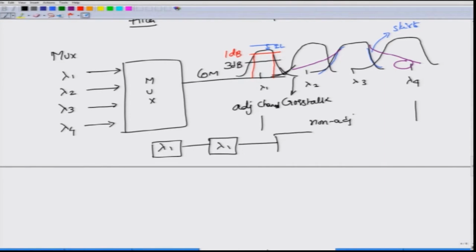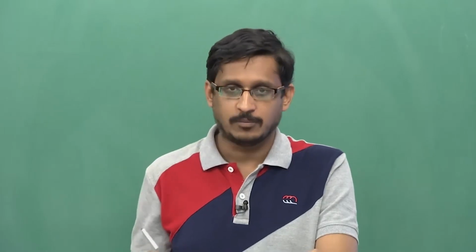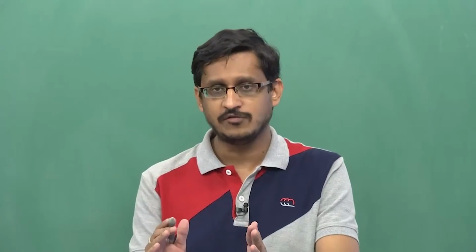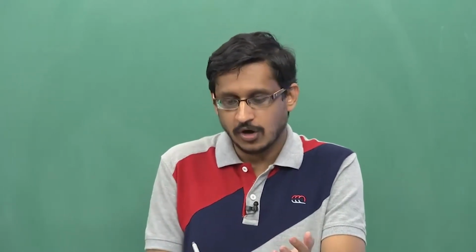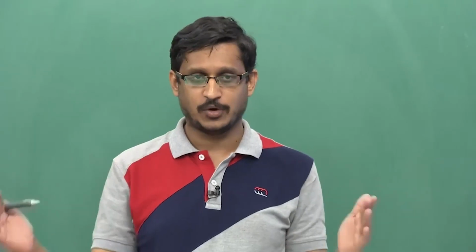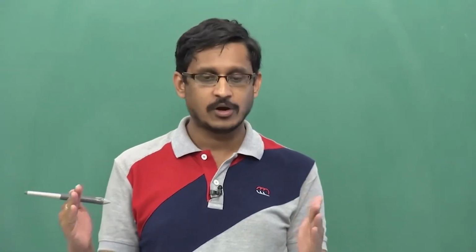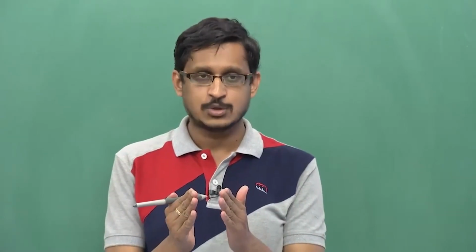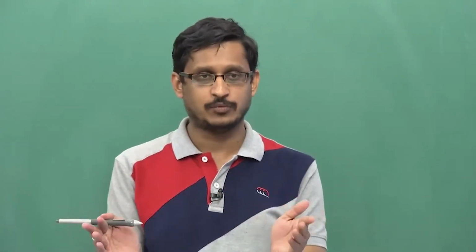them, something that happens when you are looking at a long distance transmission: at each span, just before the inline optical amplifier, you will put an optical filter in order to limit the amount of noise entering into that particular wavelength. So, overall if you see over say 10 or 20 spans of propagation, there are about 20 filters, and if you now look at the overall response of the filters, the overall response would have narrowed down. So, it might actually cut down some of the input signal spectrum.